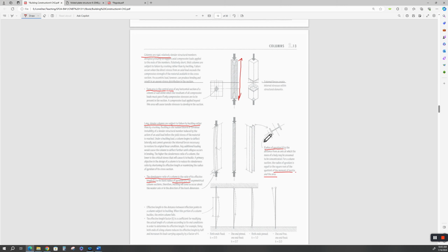When we go to look for a column or a beam, we start looking at radius of gyrations. They're in a manual. They're in a book for a given type of structure, whether it's a concrete column or it's a steel column or beam. It's in the steel manual, or it's in our concrete manuals, and we calculate that, and it goes into the slenderness ratio and the KL over R.